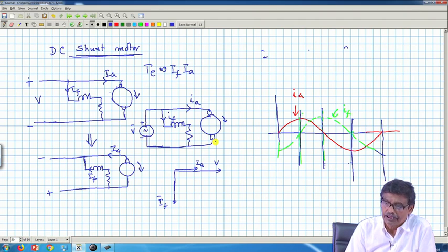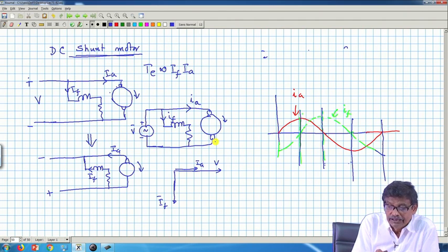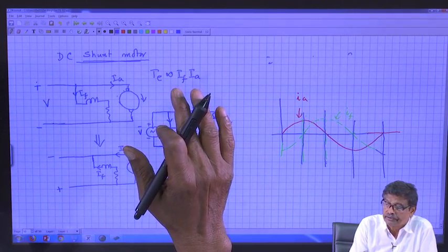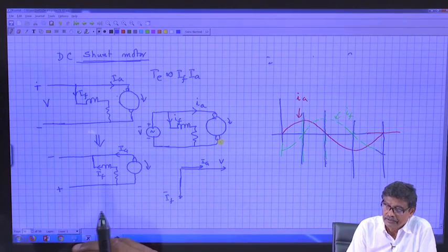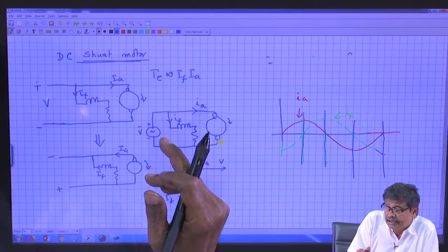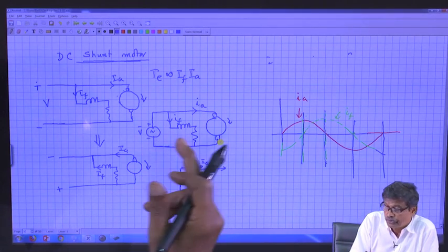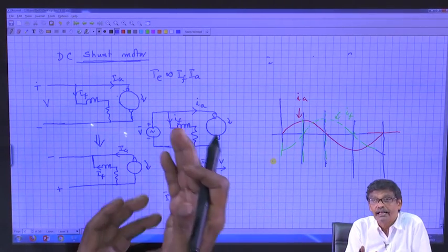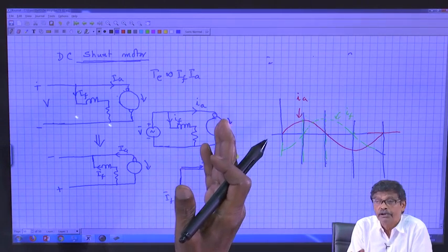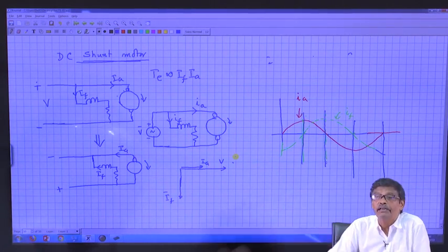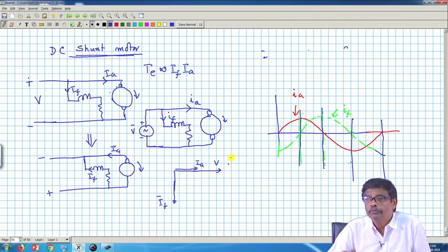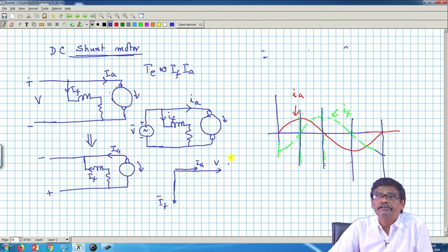So, a shunt motor: somebody may think that, knowing that if I reverse the supply voltage terminals the torque direction remains the same, I can energize it with AC voltage, 50 hertz, and it should work. But it will not, because the field inductance is very large, or omega L is very large, in the field circuit compared to the armature circuit. So IA and IF will be out of phase by 90 degrees. Therefore, the average electromagnetic torque will be 0 over a cycle, and the motor inertia will only respond to the average torque. So it will not work.